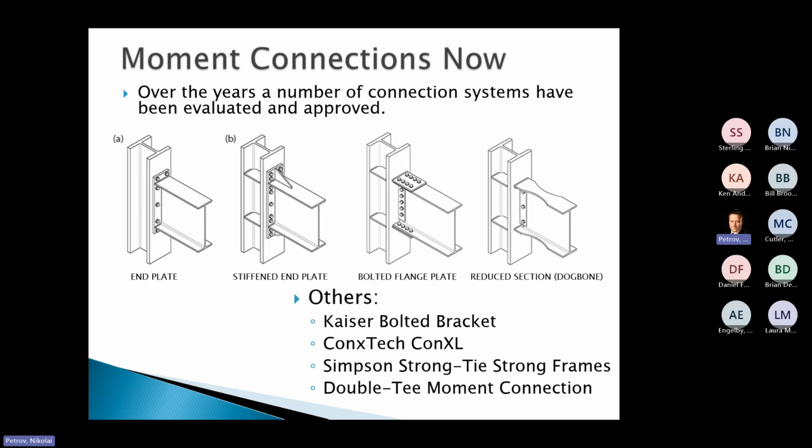But the biggest thing about them is that they make the beam not as stiff, which means it makes the frame not as stiff. And for anybody that's ever done a steel moment frame building design, you probably know pretty quickly that you don't design them for the strength that you need. You design them for the stiffness that you need. And this is a stiffness killer. So all it does is it drives up your column sizes like crazy. You get a really big beam size and then you cut a third of it away. And it's just a really expensive and messy connection.